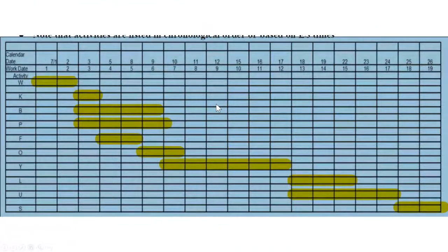Right, so we are basically doing a bar chart. We started by doing this bar chart for the main contractors, but I think what we have ended up with is a bar chart for subcontractors. It's a perfect bar chart to share with the subcontractors because it has got no float information. So this is the answer to your part B, where you are being asked to do a bar chart for the subcontractors because it has got all the float information hidden.